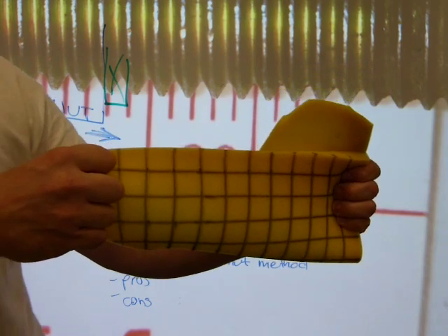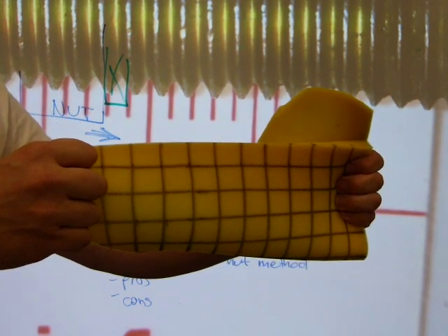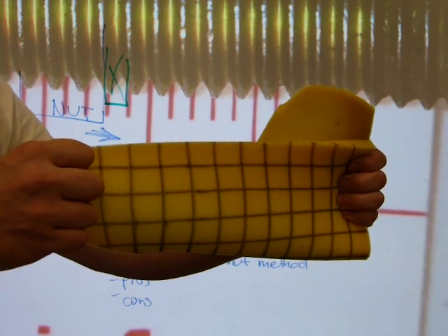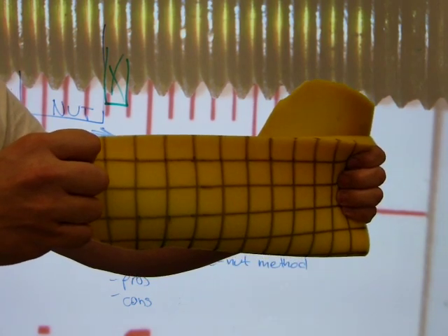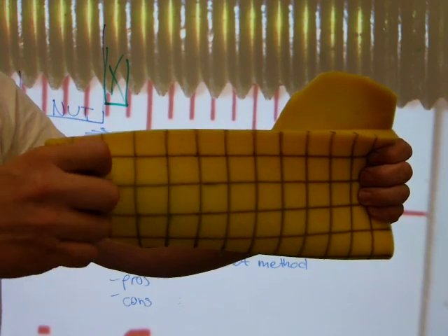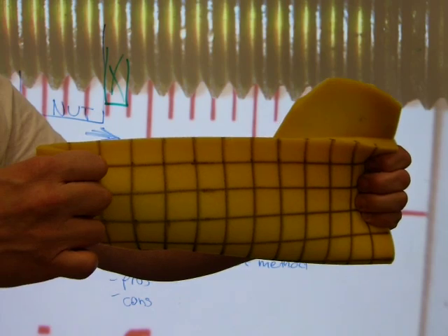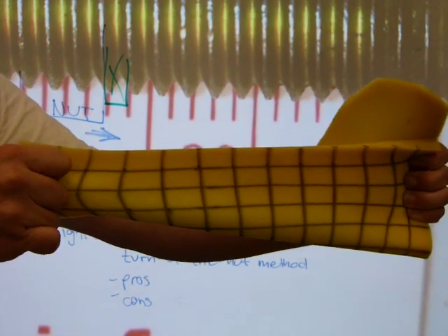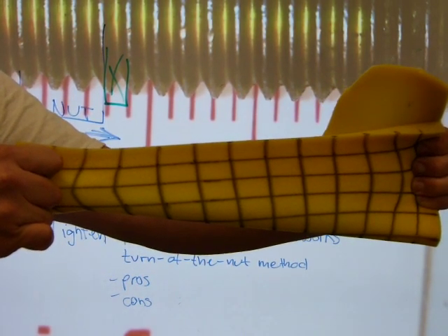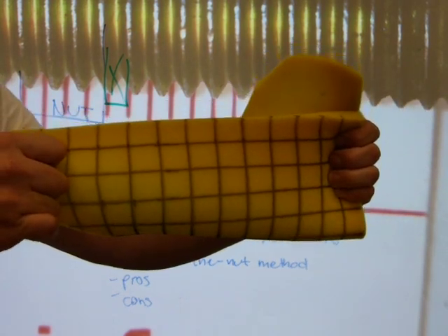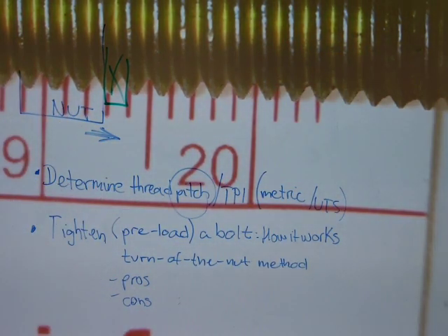If you turn this nut half a turn, it will stretch the bolt more. Like I said, if you take careful measurements on the bolt, you will see that it physically stretches the bolt. And if you take say 1 full turn on this nut from the point again where it cannot move forward and it starts clamping the material, it will stretch the bolt to near breaking point and will actually strip the threads off the bolt or the nut, whichever is softer. So that's how the concept of tightening a bolt works, or preloading a bolt.